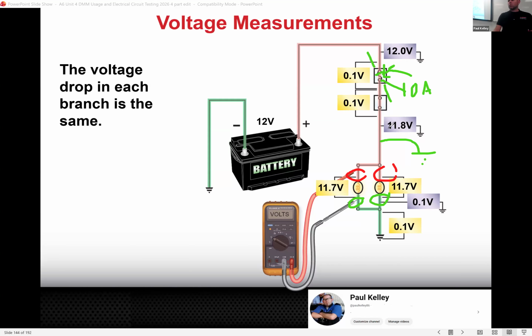Then let's just say I was totally tripped out. Let's just say I diagnosed it as 2 bad bulbs. Is it possible? Yes. Is it likely? No. So maybe because I'm just wondering, am I right on this? I'm a little freaked out. Maybe I switch my meter to ohms and I check the ohms across the bulb. How many ohms do you think I should have on each of these bulbs?